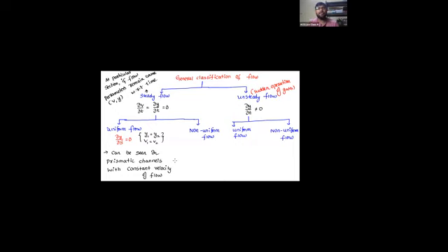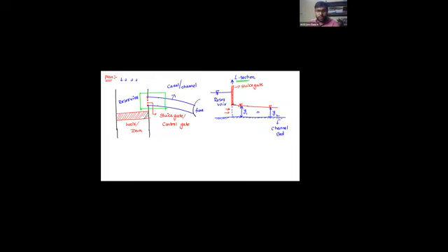We do assume it for analysis purposes, because when you take the depths to be constant, then obviously it is going to be an idealized flow. Do you think everywhere in practice the depth of flow is going to be constant? Think about that. Can you get the depth of flow constant? No. This is based upon the assumption that the flow is going to have a constant velocity or zero acceleration.